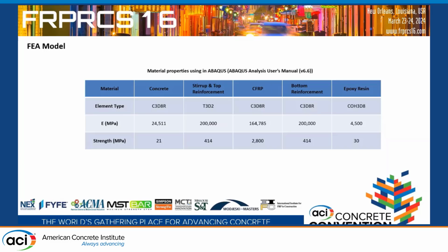So this table shows the material properties used in ABAQUS. When we do the simulation, we need to select the element type. For concrete, I used the solid element C3D8R, and for reinforcement, I used the truss element T3D2. But since I need to simulate the unbonded condition between concrete and bottom reinforcement, I used the solid element to simulate the bottom reinforcement.